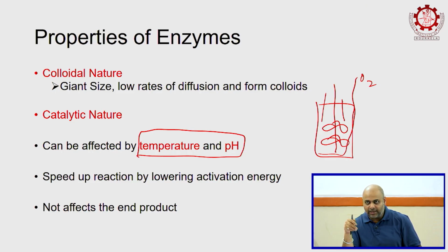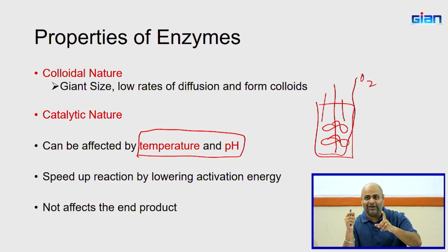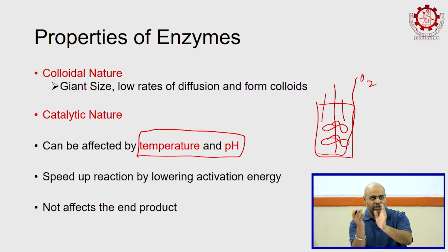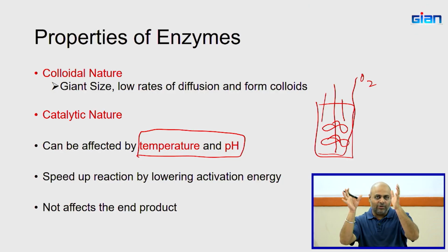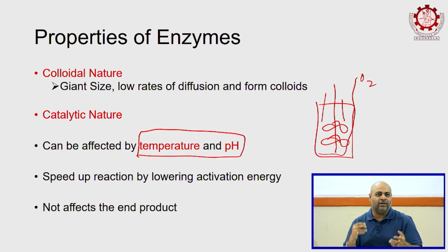Now, will the enzymes get impacted by the impeller speed? Just guess. Maybe, but it is highly unlikely, because impellers are not moving like regular fans, the ones which are running around here, but they are just pretty slow. It's mostly to maintain the homogeneous mixture of the medium, or to make sure that oxygen is diffusing throughout the medium. So, when we come into the design of the reactor, you will see when we are talking about mass transfer, how we want the oxygen to be diffused throughout the reactor, and that is where the impeller speed and the design of the impeller come into the picture.